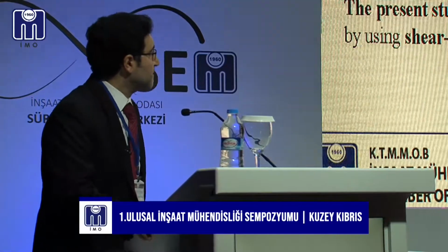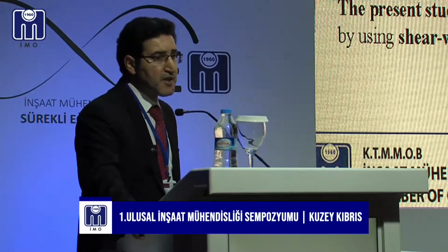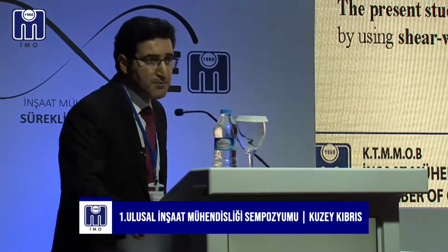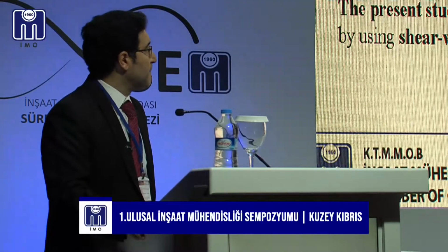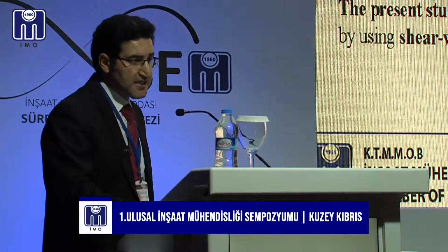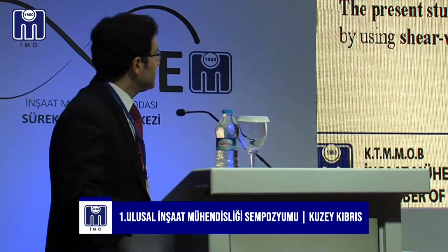This is accompanied by volume changes in the sand deposits, manifested at the ground surface as settlement, so-called liquefaction-induced settlement.